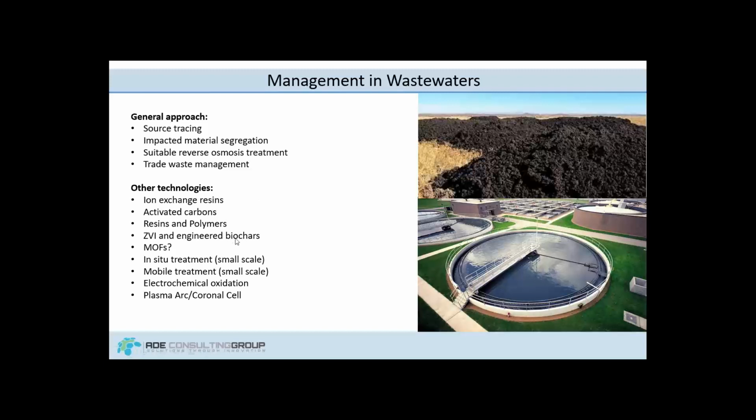So one of them that I mentioned, foam fractionation, has had really good success with managing leachates. So some of these do apply to managing leachates, but also groundwater contaminated sites. It has the advantage of not generating waste in the form of spent resins or activated carbon or similar other solids, but instead just a concentrated waste stream. There are also a number of resins and activated carbons and sorbents that are quite effective. Unfortunately, these do require disposal as a solid, or they can be destroyed by plasma arc or something similar, or incinerated.